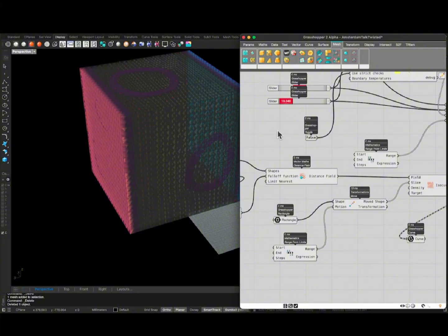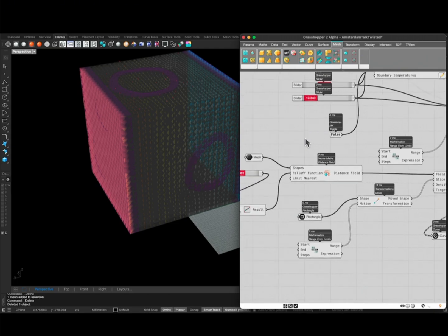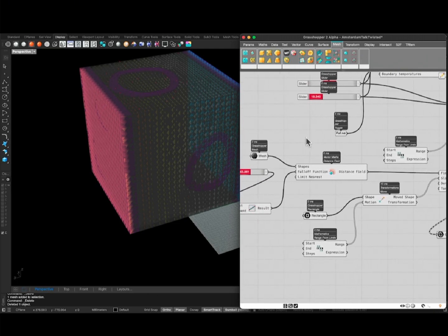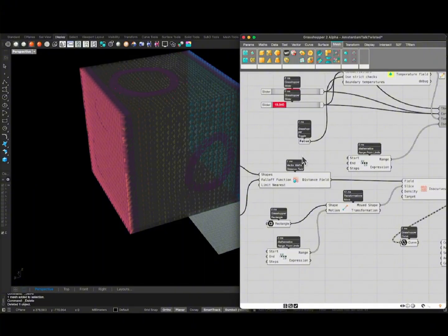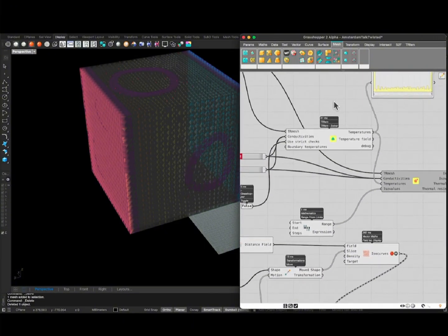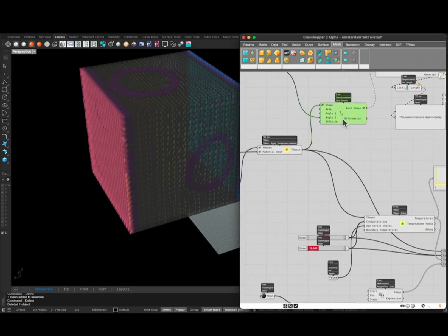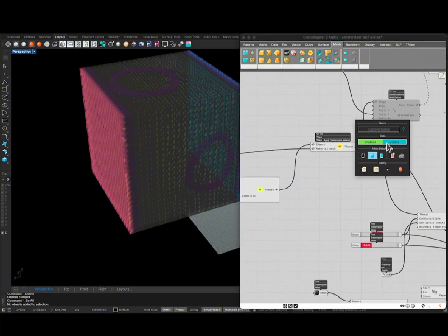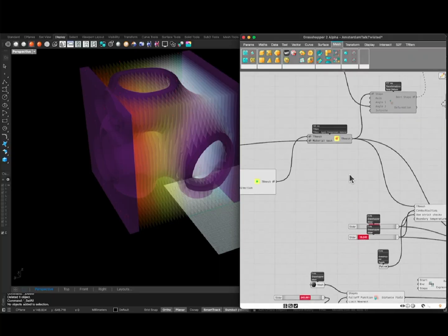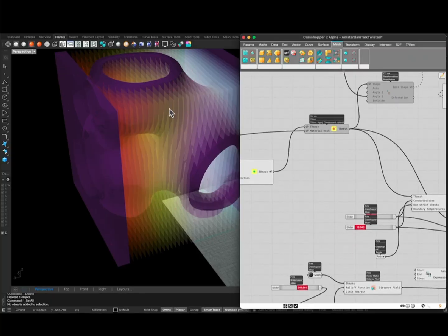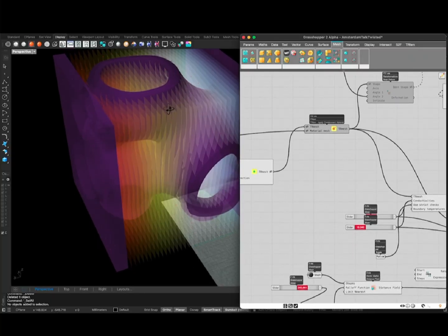When we now try to make such a mesh available for an actual finite element analysis, then what do we do? Well, let me disable this one here. And let's turn off the preview for this one so that we see what's going on again here. All right, so we need this tetrahedral mesh for the thermal analysis.